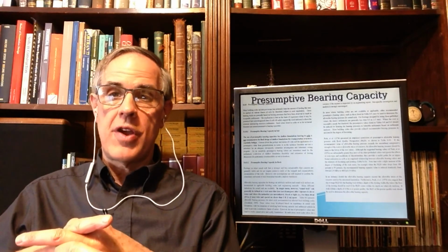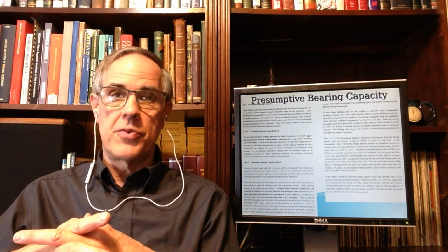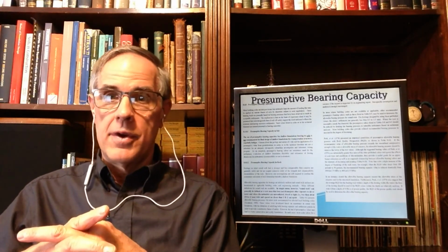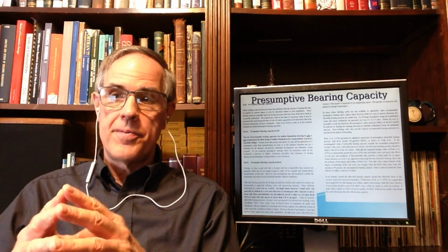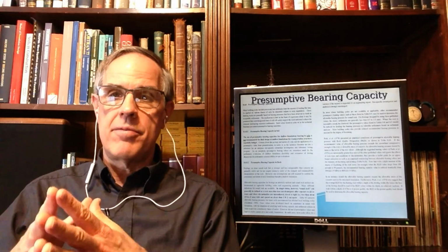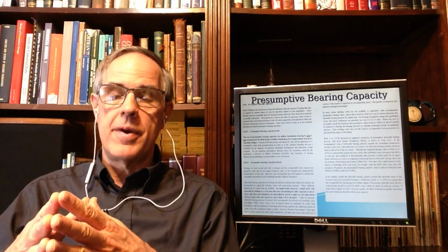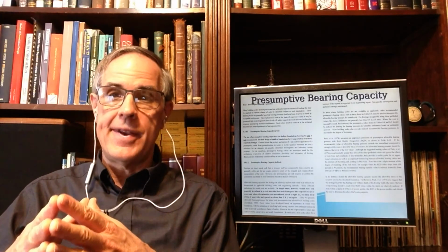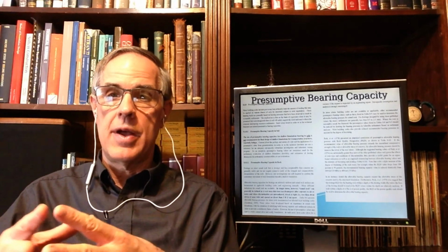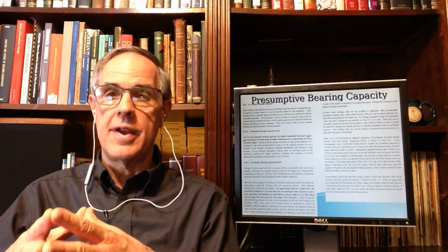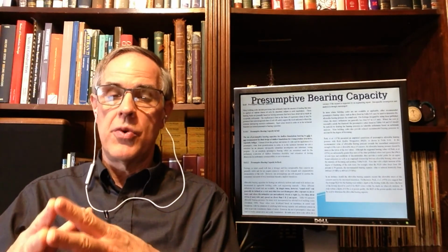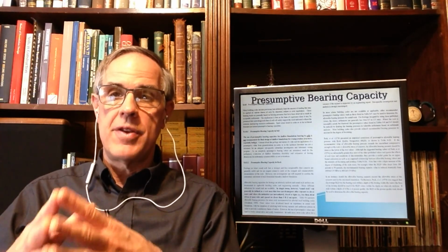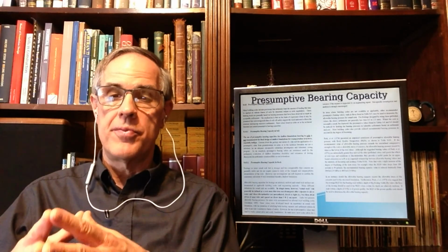Presumptive bearing capacities also took into account settlement issues, which were not fully understood then either. So in soil, I think that presumptive bearing capacities are out of date. I believe that I would not use them as a design technique. In some parts of the United States and some places in the world, you will still see them enshrined in codes, and you have to work around that.